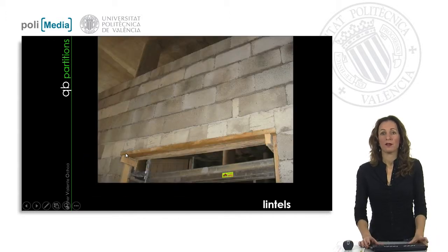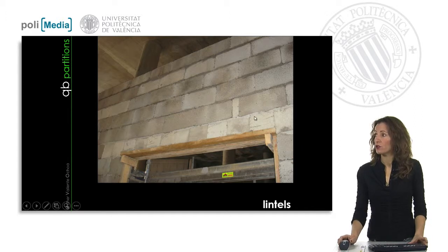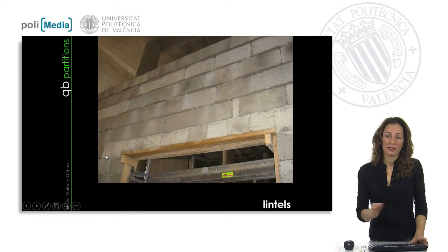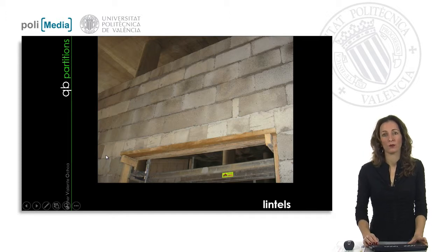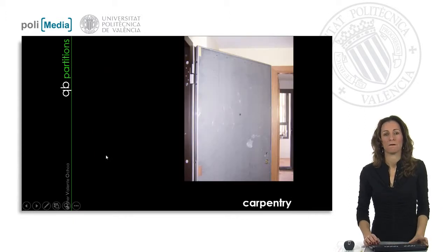Some lintels are made on place, fixing them into the brick walls. We fix it inside the mortar with some rebars that create the lintel on site. This is okay also, but we have to check if the final resistance is enough for the brick wall we are building up on top of this lintel.